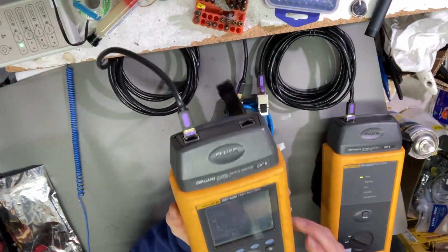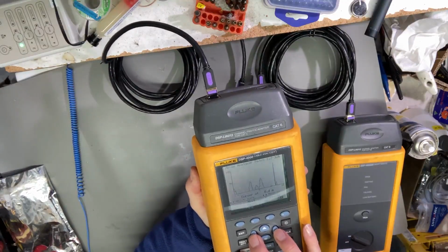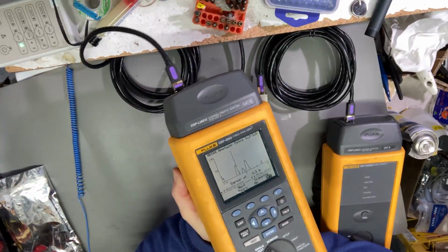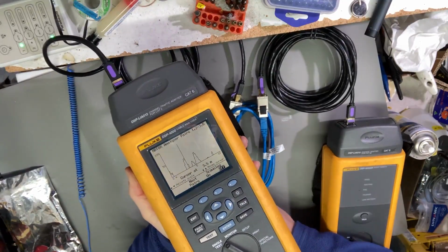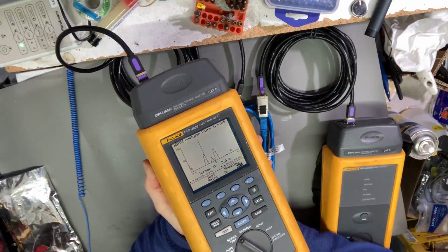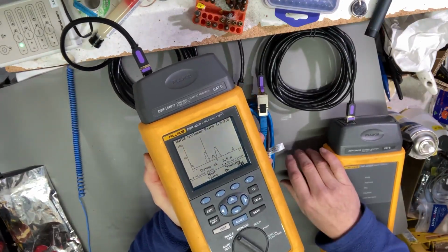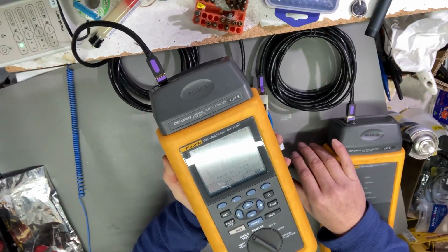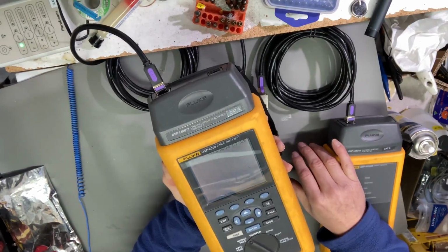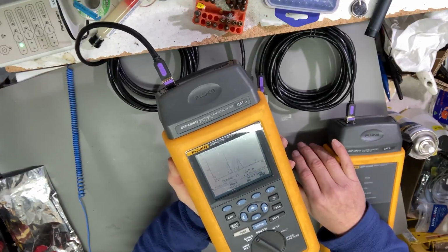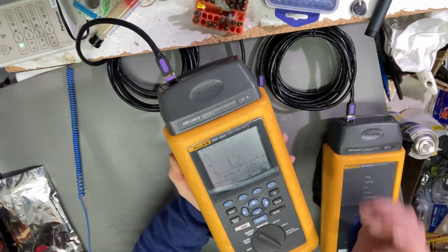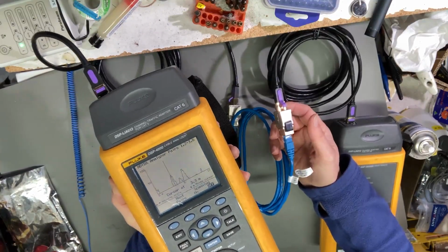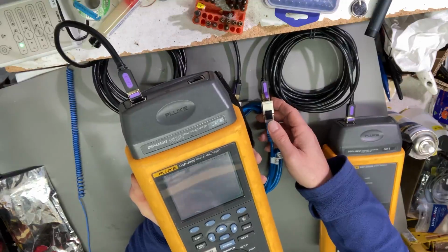If that was in a wall or somewhere and you're wondering where should I cut a hole in the wall to inspect for physical damage, well, especially if you calibrate it, generally over a few meters it's going to be accurate within plus or minus 300 millimeters. So that will tell you where in the wall to cut, if you are in that situation. But more likely, cables normally fail at a connector or a coupler, but again, you may have water ingress or someone has damaged the cable.